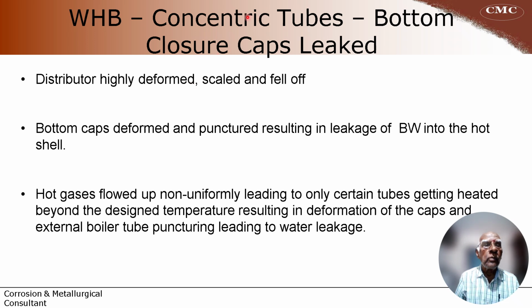These are the steps involved. The distributor highly deformed due to high temperature and scale, and fell off. The bottom caps deformed and punctured because they were non-uniformly heated. Not all the tubes are uniformly heated, only certain portions were heated.